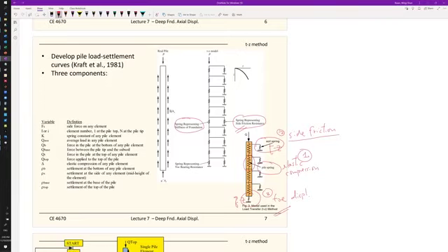Remember the consolidation theory we learned from Terzaghi; Terzaghi also used a spring analogy to describe the consolidation response. Same here, like the soil-pile response. Coyle used a series of springs to mimic that, and also we have a spring representing the toe bearing resistance. We only have one spring for that,